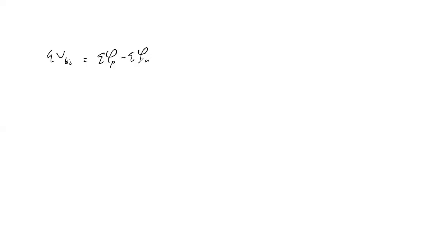So the built-in potential here is the internal potential energy required to cancel out the diffusive flow of carriers, which we already mentioned. And as such, we're able to have that depletion region. It's more like it creates a balance.